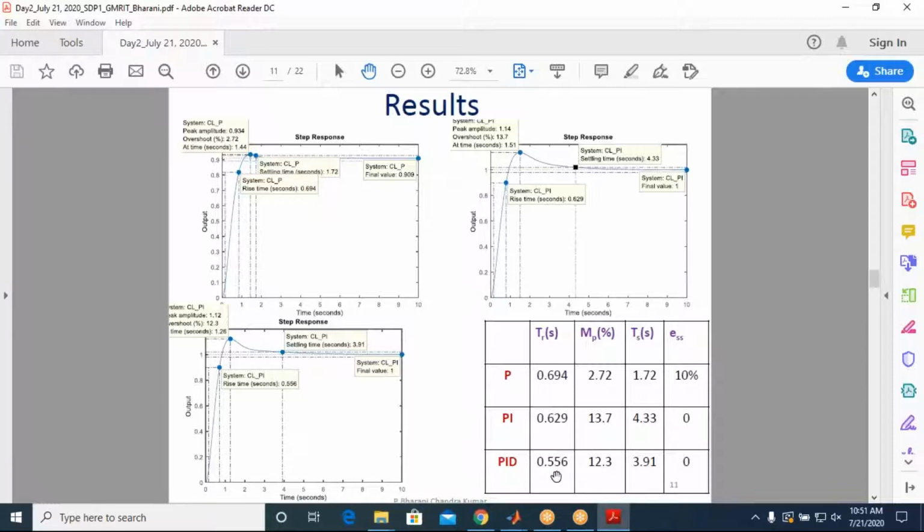So I cannot keep changing the KP, KI, KD values to get unrealistic specifications. If I am using the integral action, wind up saturations will come into the picture. To handle that, there is a method called the anti wind up controller for the integral action. So that is my answer.